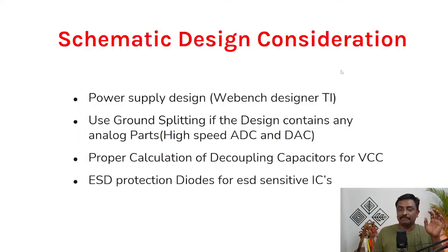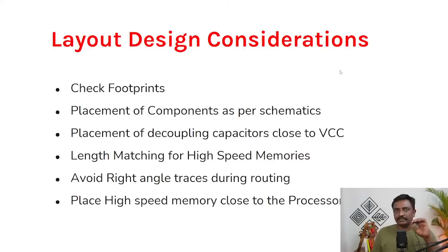Okay, the next is the layout design considerations. You have to check the footprint's actual size, and the placement of components as per the schematics. I will go into much more detail about layout design considerations during the PCB design sessions, which are happening on day 11 to day 20. So placement of components as per the schematics, placement of decoupling capacitors close to the VCC pin, and length matching has to be done whenever you route high-speed memories like DDR, SDRAM.